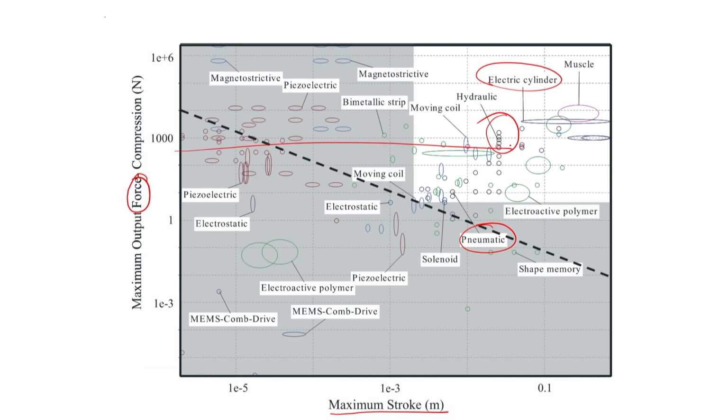If you think of a large displacement, not large, a very large force, then you have options like shape memory and electroactive polymers. And if you are thinking of a moderate force level, not moderate deflection, then you have these piezoelectric materials with you. Okay.